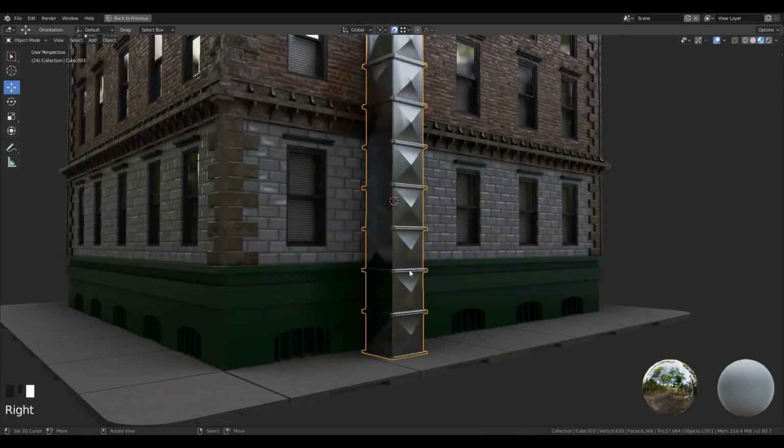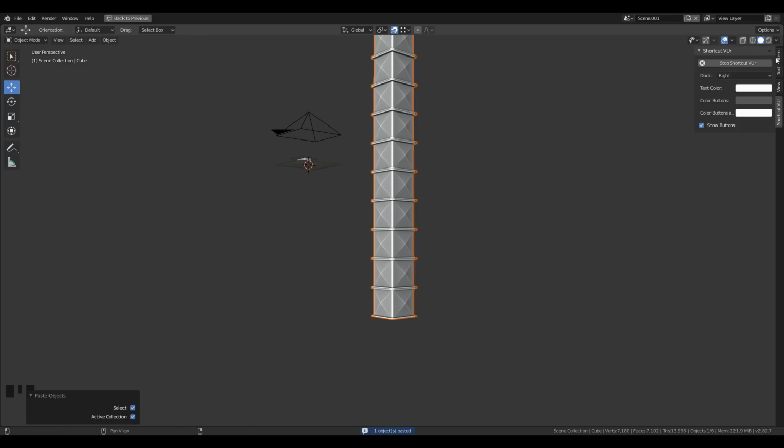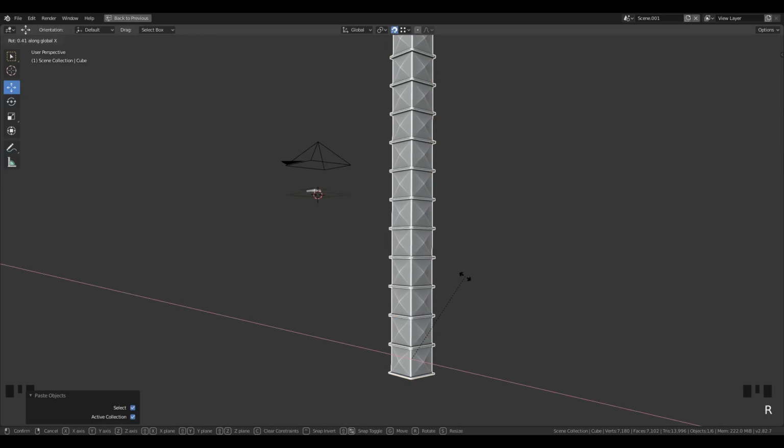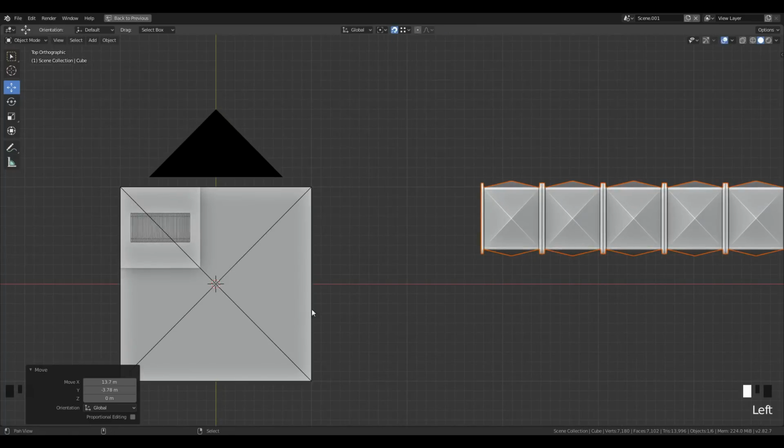Then just like previous tutorial, select the mesh and press Ctrl C to copy it and paste the mesh in scene 2. Then lie it down and snap it on bottom left edge of the plane and make it shorter by decreasing the value of array.